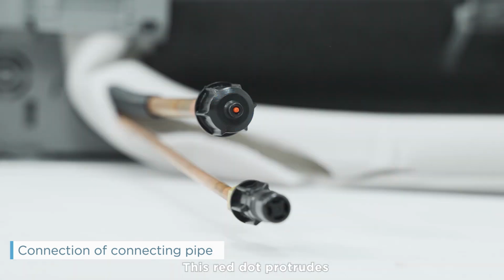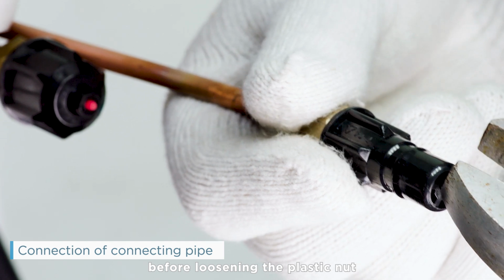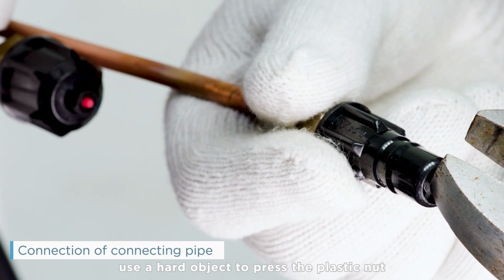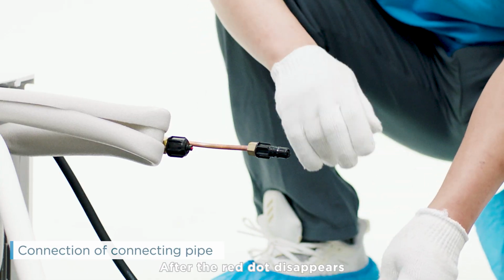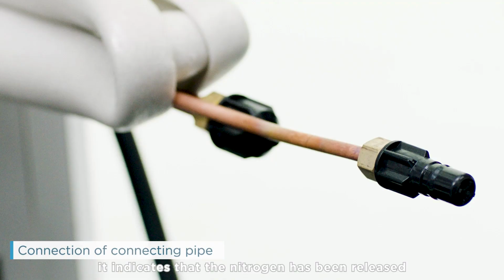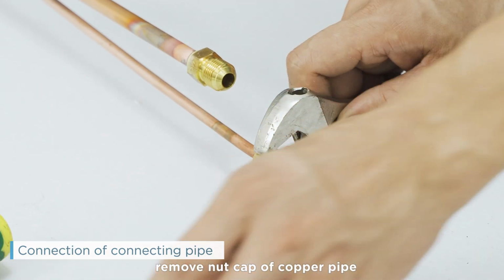This red dot protrudes, indicating that the evaporator is filled with high-pressure nitrogen gas. For safety reasons, before loosening the plastic nut, use a hard object to press the plastic nut at the nitrogen filling port. After the red dot disappears, it indicates that the nitrogen has been released, and then loosen the sealing nut. Remove nut cap of copper pipe.